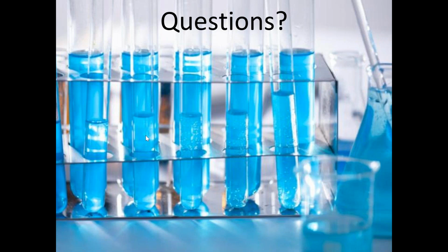Question, can we have a neutral pH and low alkalinity? Absolutely. That can just mean that you don't have a lot of acid in your water. You don't have a lot of alkalinity, you just have a little bit of a tighter balance versus a lot of acid and a lot of alkalinity. You just have less of both, and that can still add up to a neutral pH.